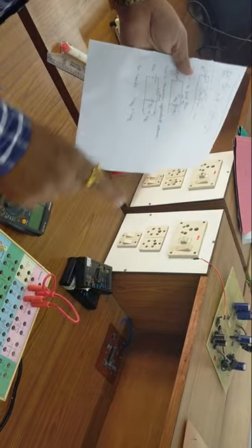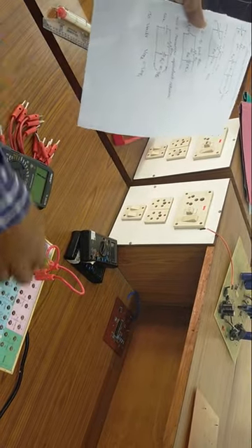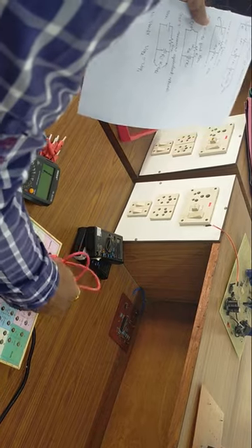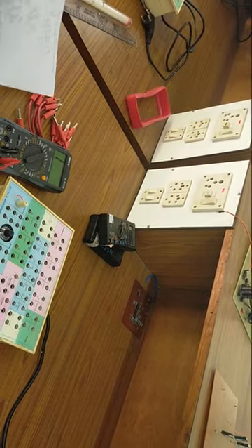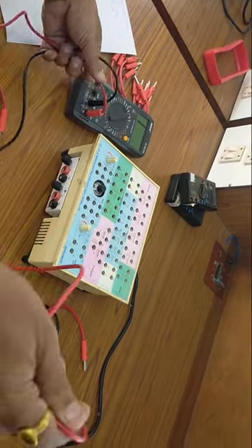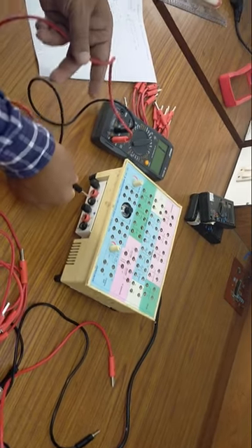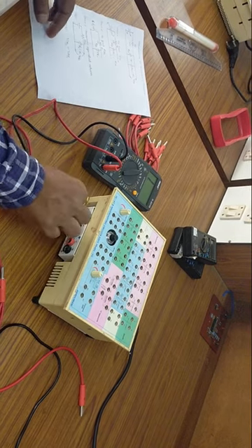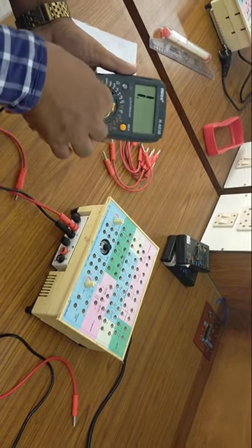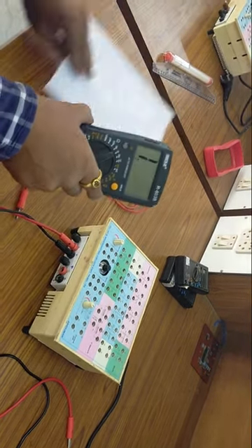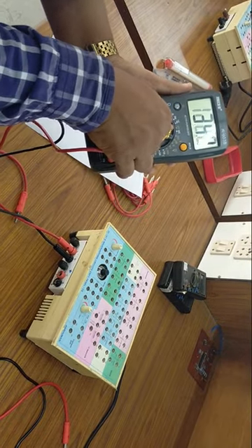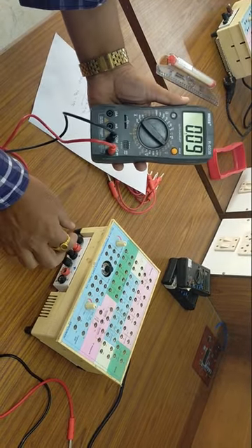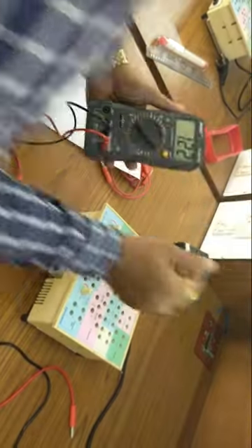Before that, we have to set the value of ETH. How to set it? For that purpose, we will use the multimeter again, because we adjusted that value earlier to 15 volt. Now we have to adjust it to ETH equal to 7.5 volt with the help of this knob. Switch on this kit supply.